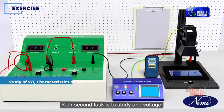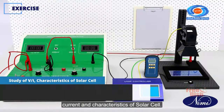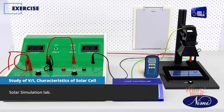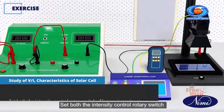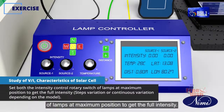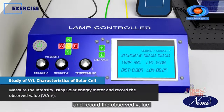Your second task is to study the voltage, current and characteristics of a solar cell. To perform this task, you need a solar simulation lab. Connect the solar simulator equipment to mains power supply and switch on. Set both the intensity control rotary switches of the lamps at maximum position to get the full intensity. Measure the intensity using the solar energy meter and record the observed value.